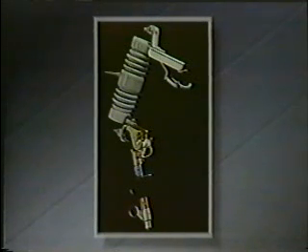Again, when a sectionalizer operates, the probability is extremely high that a permanent fault exists. Repair it and reinstall the sectionalizer. Do not use the sectionalizer to close in on a fault. If no fault is found after an operation, use your company's standard safe working practice procedures before closing.